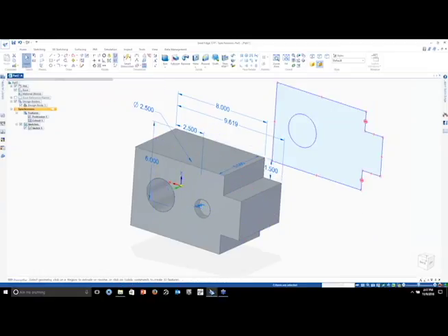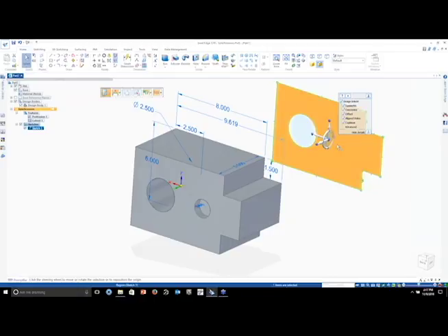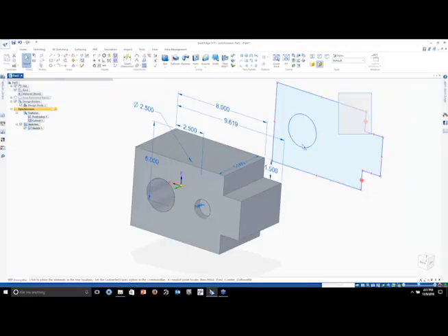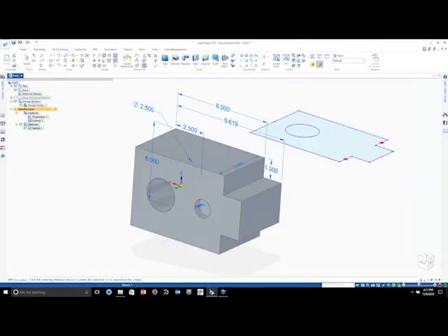Typically in an ordered environment, if you're coming from SolidWorks, if you delete a sketch that a feature is based on, well, that feature disappears. Same with ours. All right, because this is synchronous, it doesn't require the sketches. If you do want a sketch, at any given time, again, you can right-click and say Restore Sketch. Remember, I mentioned earlier, if you want to grab a sketch from the Pathfinder, it allows you to drag it. So I can go ahead and drag that sketch out here if I wanted to use it again.